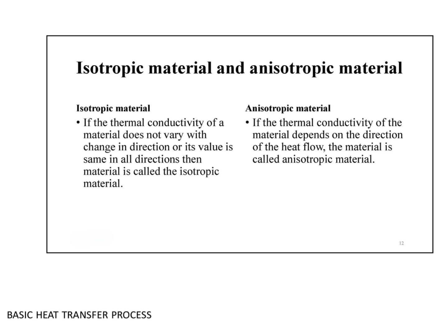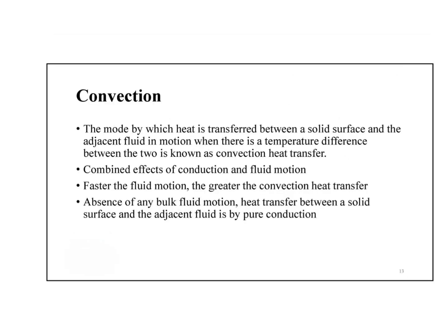Moving to next slide. Convection. Convection is the transfer of heat between a solid surface and a moving fluid due to a temperature difference. It involves both conduction and fluid motion. Faster fluid motion increases convection. If there is no fluid motion, the transfer happens by conduction.